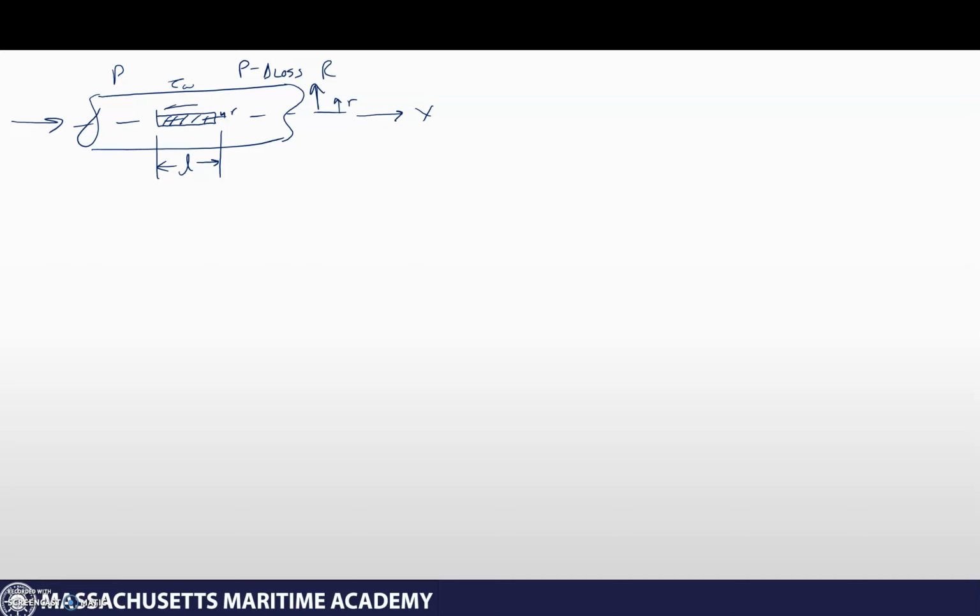What we have is a back pressure. That'll be pressure times pi r squared, little r because we're just looking at the element, and then we're going to integrate that over the whole pipe. And then I have my front pressure, which will be acting the other direction, so minus P minus that pressure loss. Since we are losing pressure with respect to the x direction, we're just going to call that dp dx, and we will also multiply that by pi r squared.